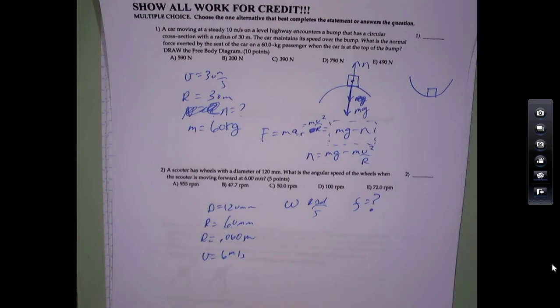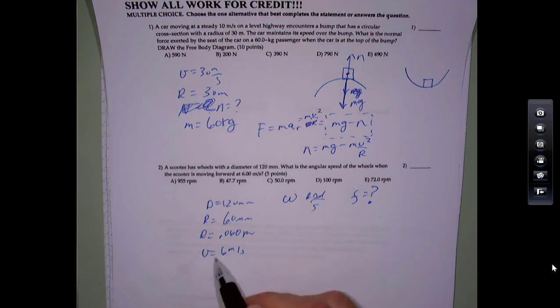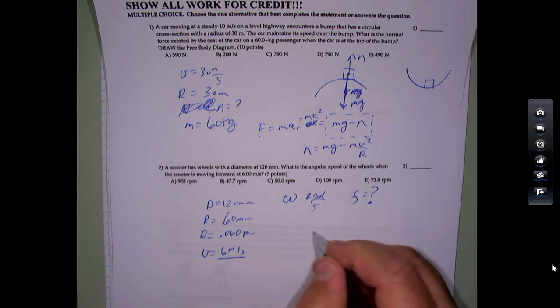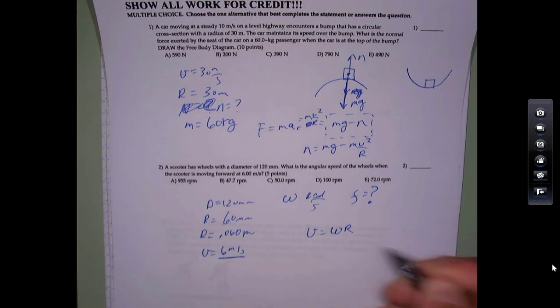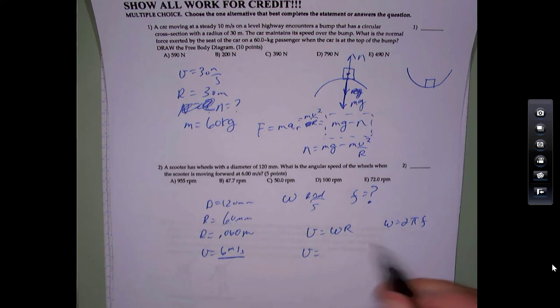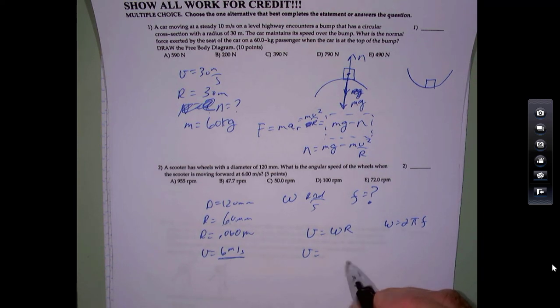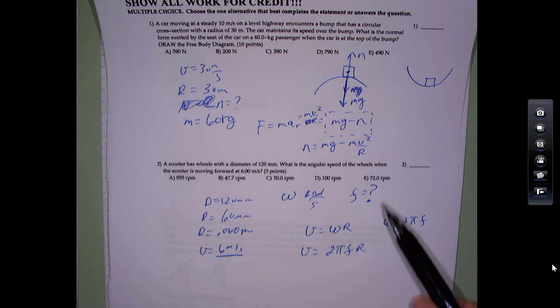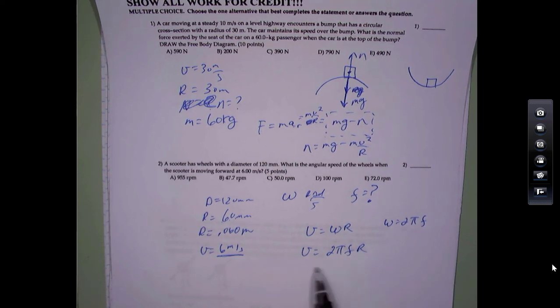Okay, so we know the relationship between tangential speed, that's what this is called, our regular old speed that we had before, and angular speed. So V is equal to omega times R, and then we also know omega is equal to 2 pi f. So if we want, we can put that in here for omega. So let me do that. 2 pi f times R. Okay. So good. The only thing that we don't know then is the frequency, and we can solve for it here. Be careful. This is revolutions per minute. The way that we're doing this now looks like it's going to come out to be revolutions per second. Then we'll have to convert it to revolutions per minute.